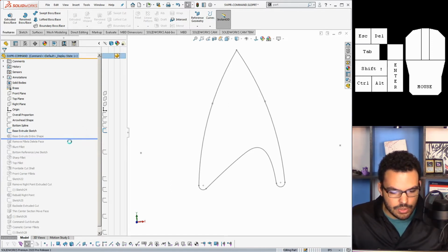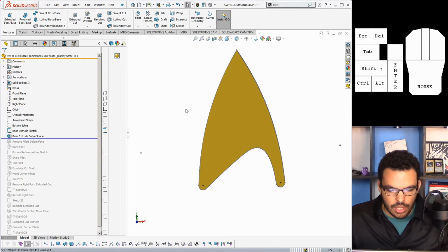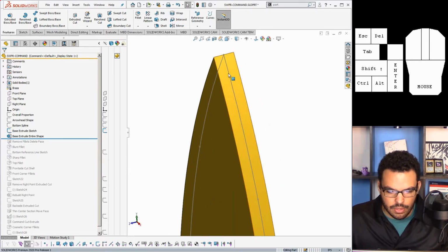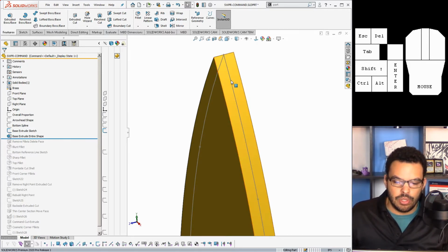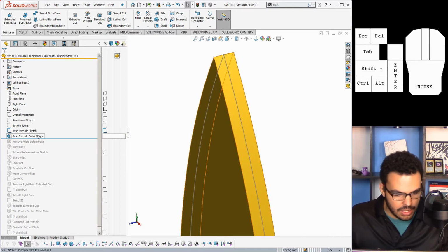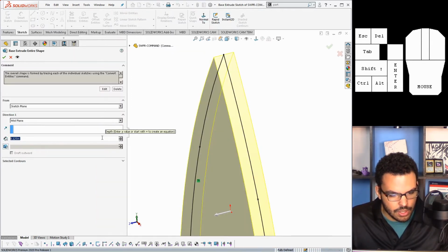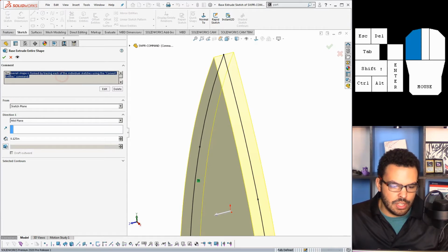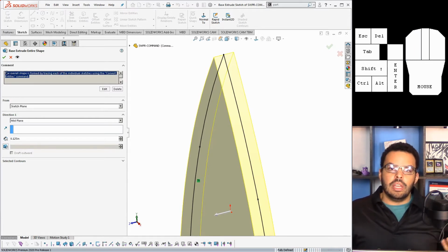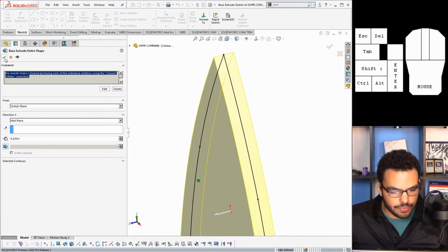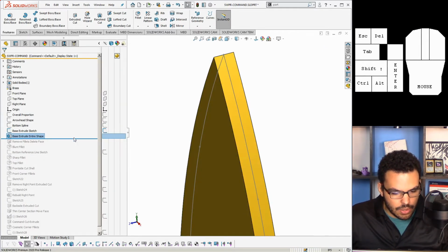But let's go ahead into the base extrude, and looking at the sketch here, it was done with respect to the mid plane, which is good. I always recommend to do that. It makes mirroring things a lot easier. So that's very good technique there. Let's see if anything interesting was done here. Yeah, and actually, this thing just explained the thing that I did. So, those are my sleuth abilities that I've developed over the years. So I hit OK to that.